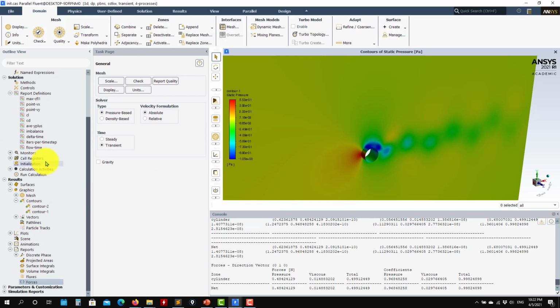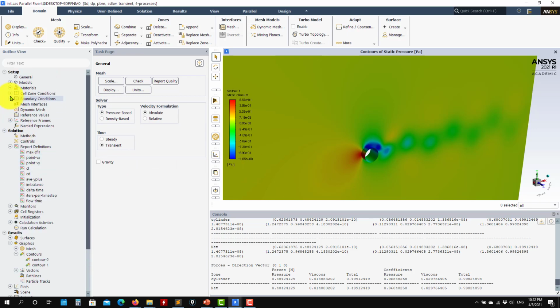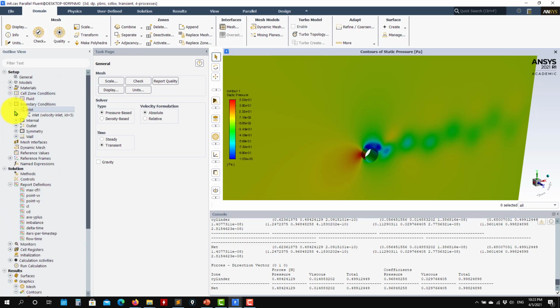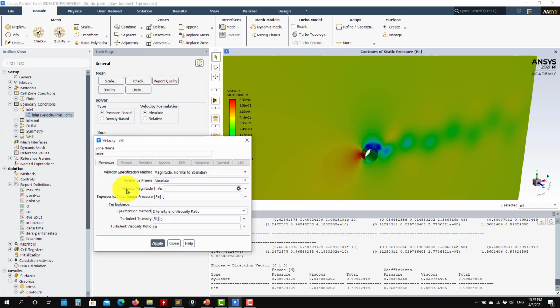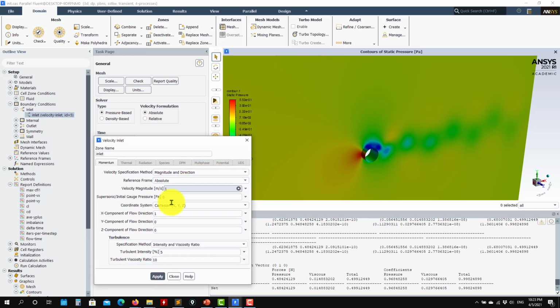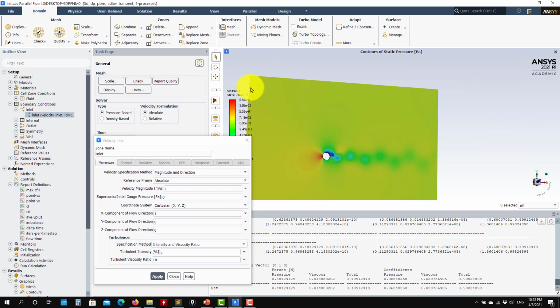The other way, for instance, is that you decide to run the case, and instead of changing the geometry, here you can change, you see that you have normal to the boundary, but you can give magnitude and direction. So if you decide to change the angle of attack by changing the inlet velocity, you need to add this transformation.